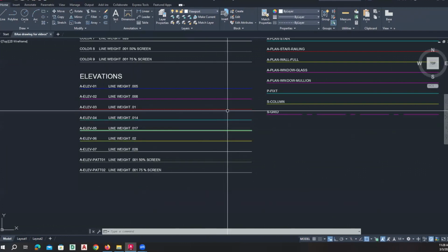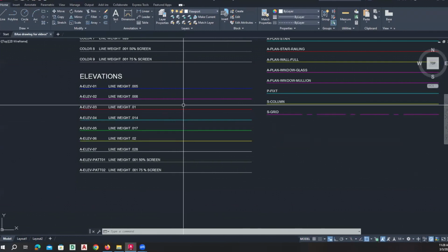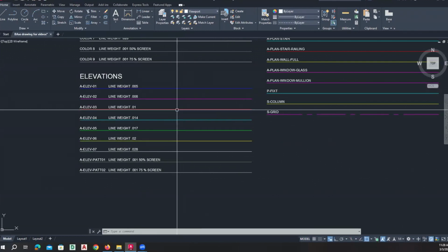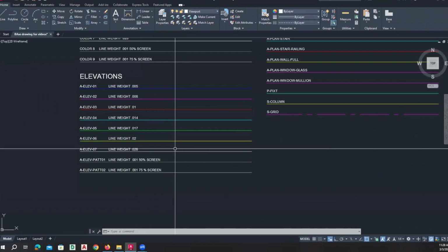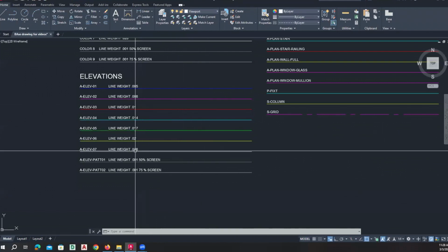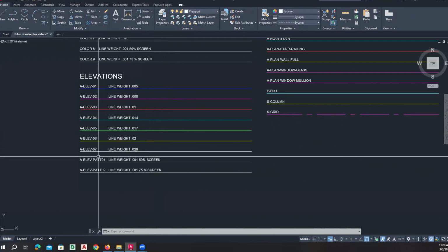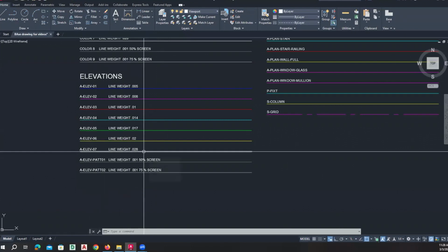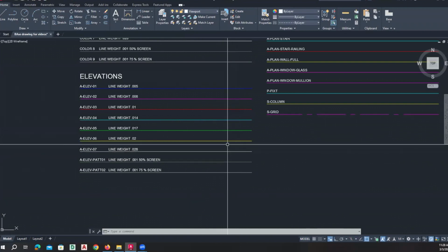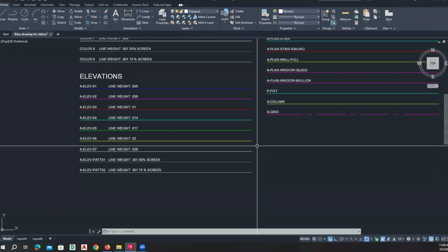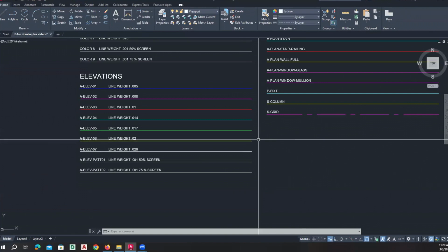And also the colors, right? As much as possible, the colors tend to be brighter on the screen as the line weight goes up, right? So the thinnest line is blue, which to some may seem very dark, similar to the black background. And the heaviest line weight, 07, which is 0.028, is white, which is a fairly bright color in terms of contrast with the background, right? Maybe not so much in terms of vibrancy, but certainly contrast to the background, which is typically black.